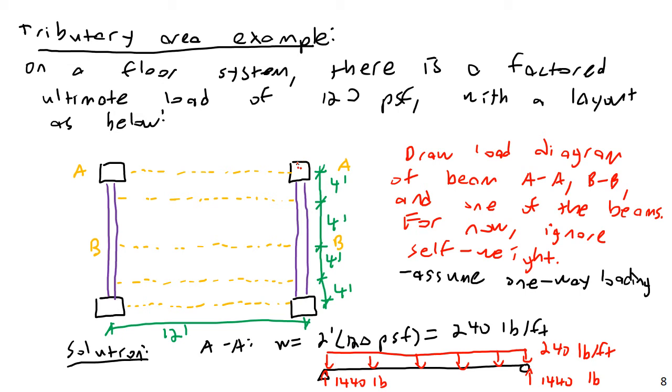I mean, good. You're looking at the column. We're looking down. So I'm not sure what you're asking exactly. Not the top one, the second one. This is not a column, this is a girder. In black we have the columns. Okay. Distance between the column and the first beam. Oh, you mean the center line of here to the center line of here. As the drawing says, it's 4 feet right here. It's 4 feet from the center of the column to the center line of this beam.